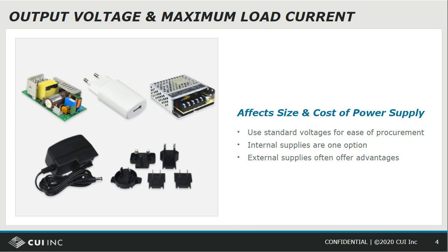The output voltage and the maximum load current also may affect the choice of an internal versus an external power supply. And our recommendation on the output voltage, first off, on either class, internal or external supply, is to use a standard output voltage for ease of procurement. And by standard output voltage, what we're referring to is something like maybe 12 volts. It's more common than 9 volts, although 9 volts is fairly common. But if you go to something like 11.3 volts, that's definitely not a common voltage, and it'll be harder to procure power supplies with strange output voltages.